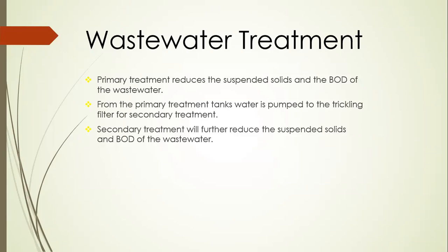Right. Then, as I indicated, the main target of primary treatment is to remove the suspended solids and only a relatively smaller part of BOD removal. Then, whatever the settled material, we call it sludge, is removed from the system and sent for further processing.